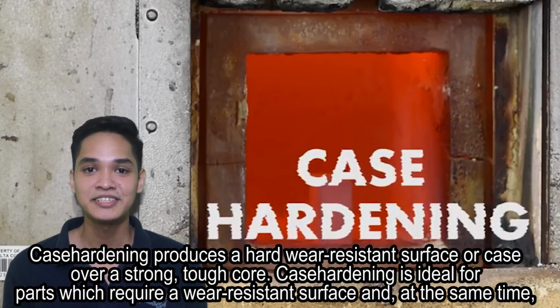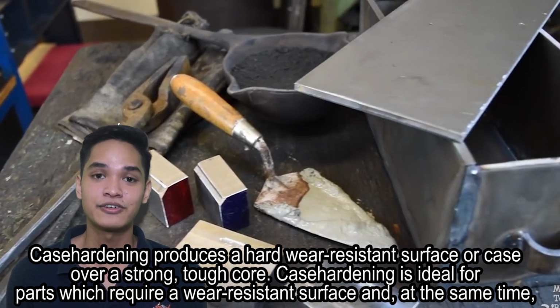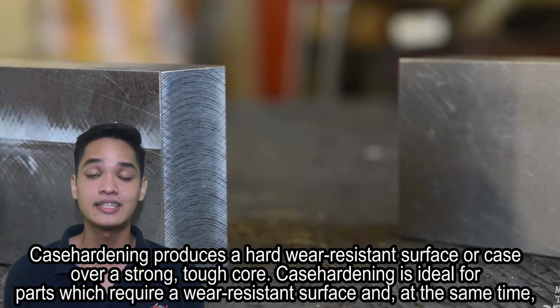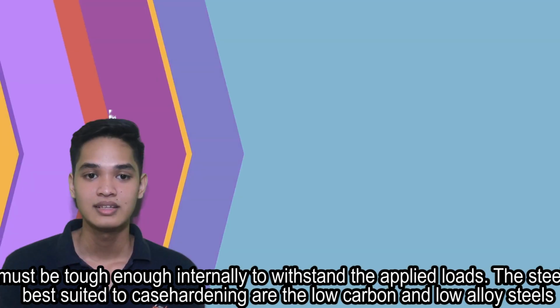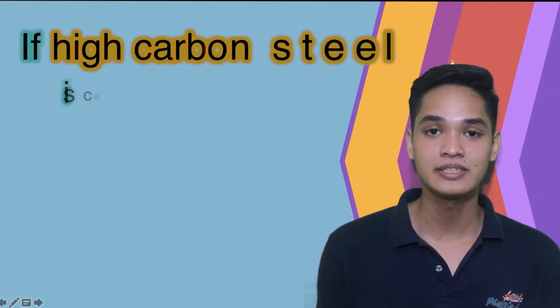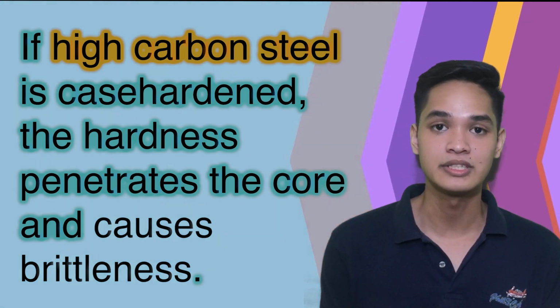What if, when heat treated, the surface responds to hardening while the core toughens? The case hardening process produces a wear-resistant surface or case over a strong, tough core. Case hardening is ideal for parts which require a wear-resistant surface and at the same time must be tough enough internally to withstand the applied loads. The steels best suited to case hardening are the low-carbon and low-alloy steels. If high-carbon steel is case hardened, the hardness penetrates the core and causes brittleness.